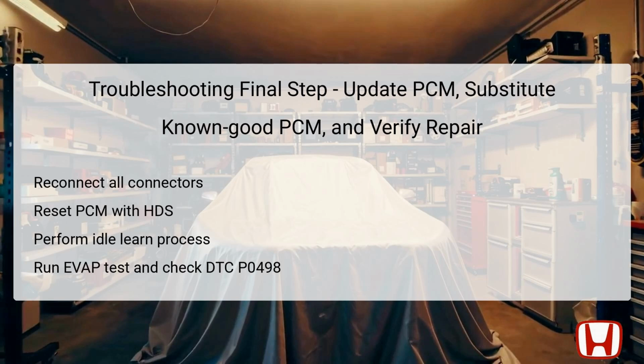If the DTC P0498 does not reoccur, the repair is successful. If problems persist, replacing the PCM with a known good unit or updating software might be necessary, followed by a thorough verification to confirm the system functions correctly and the fault is cleared.